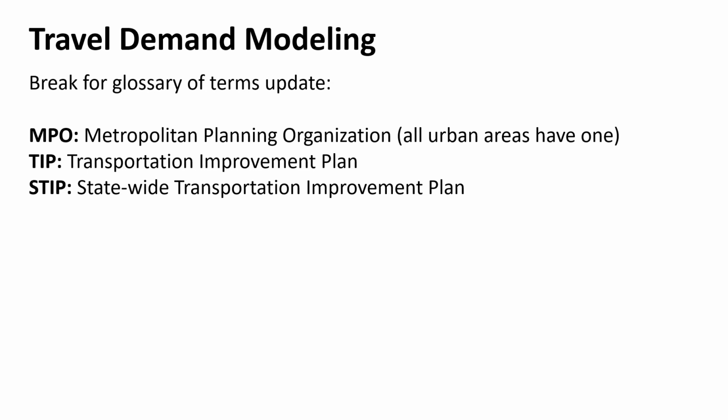These MPOs then report this to the state. In Indiana, it's INDOT, and they put it into their statewide transportation improvement plan, which is the STIP. It's at a large scale, obviously, so it's not going to be fine-tuned. We can't tell exactly what the traffic on Sturdy is going to be, but they do have a statewide planning model. At the state level, they're more worried about intercity trips, and how much traffic is on interstates and state highways and so forth. But that's based off of these smaller plans which come out of the MPOs.